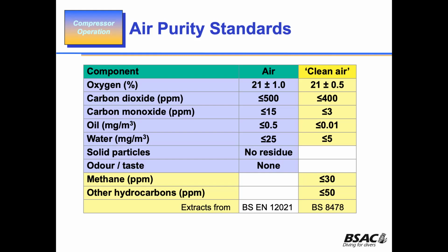The same reason that the hydrocarbons are so low. You don't want any oil at all in that cylinder, so that when you start poking high pressure oxygen into the cylinder, you don't get a quick bang. So that's what you're looking for, right?